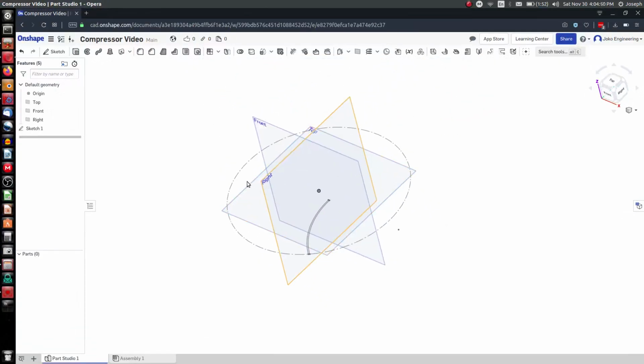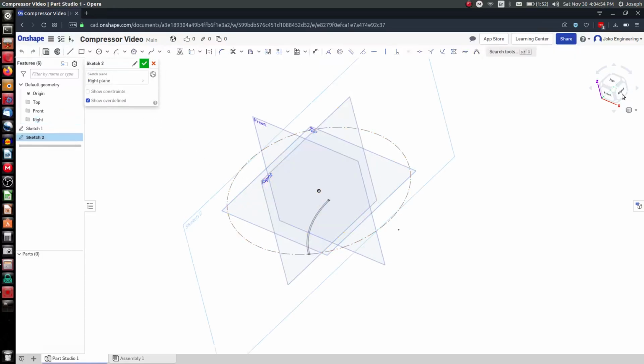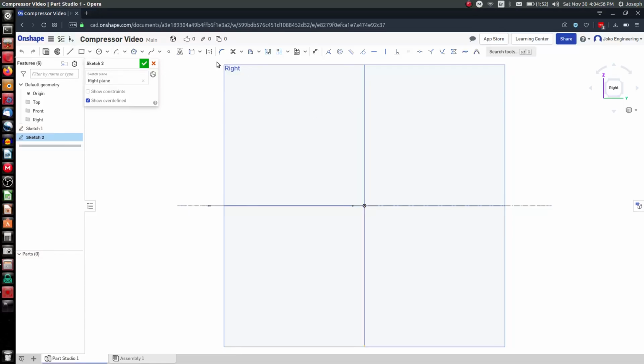Let's go to the right plane sketch, and viewing from the right, I put down a very similar rectangle. I can use the super secret S key to bring up a menu where I can choose a dimension, and as before, vertical 0.25.